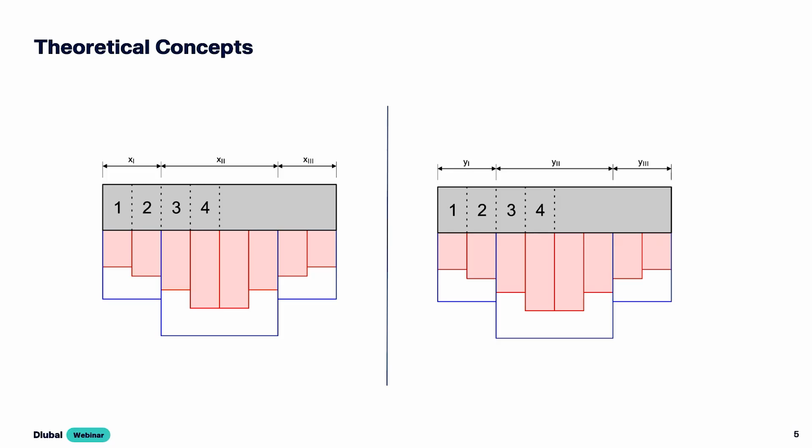So this slide shows a foundation in both the X and Y directions. The red line represents the moment distribution, and here the highest moment occurs directly below the column, while it decreases towards the edges of the foundation. And to capture this behavior accurately, RFEM divides each reinforcement direction into 8 design strips, 4 strips on each side of the column.